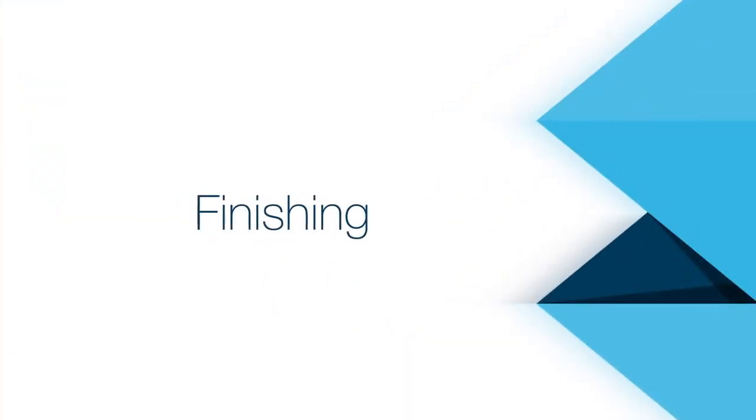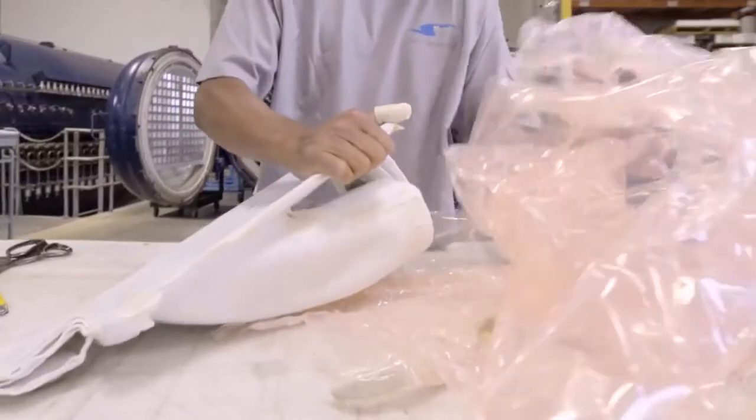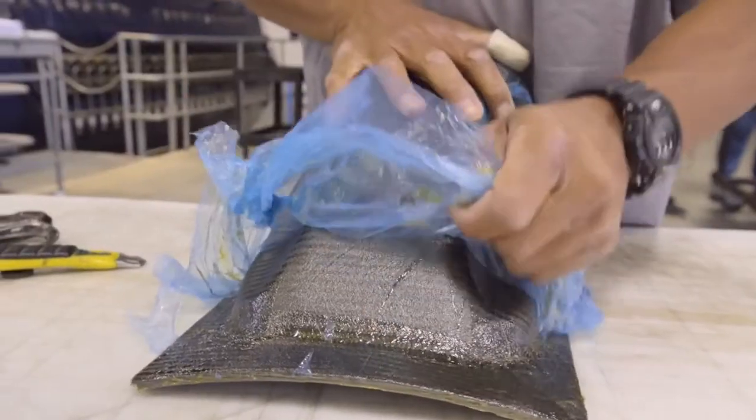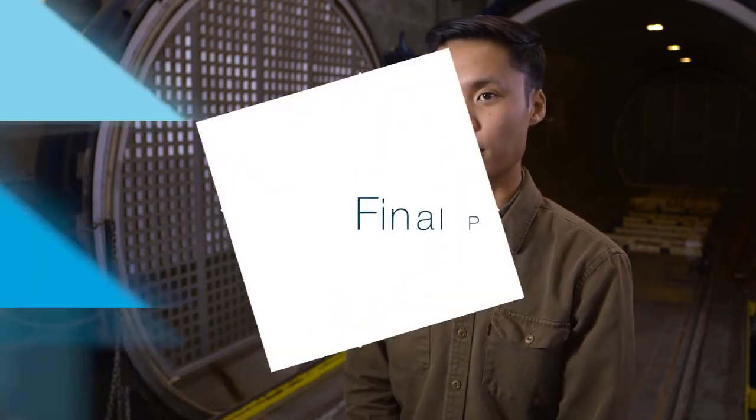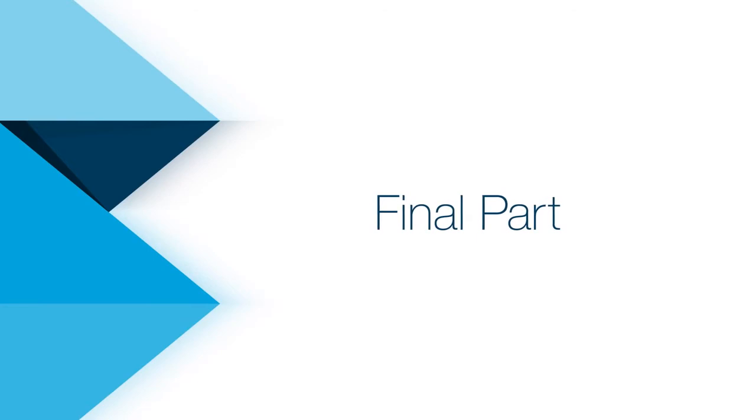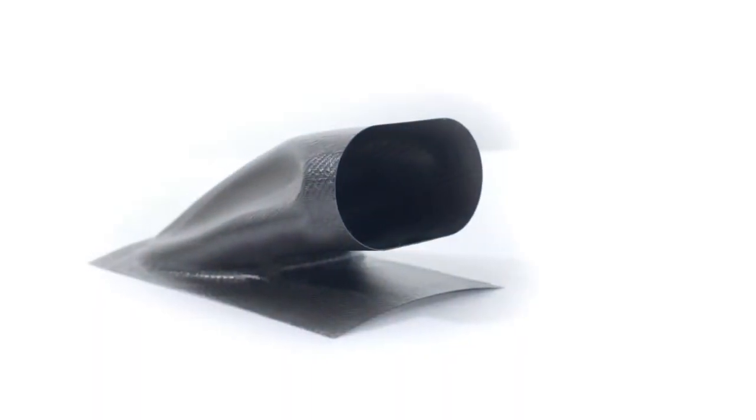After the part is cured, the vacuum bagging materials are discarded, and the tool and the part are now placed into a solvent bath for the dissolving of the tool. The solvent bath allows for a more simple and less messy setup when it comes to removing sacrificial tools. After the dissolving process, you have a finished product, which then can be bonded, trimmed, or drilled in the next level assembly.